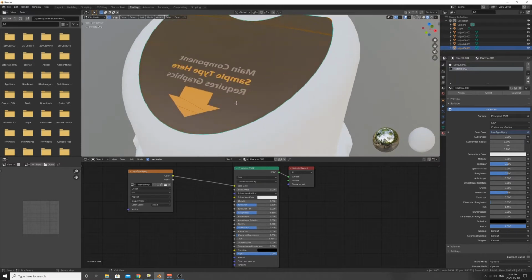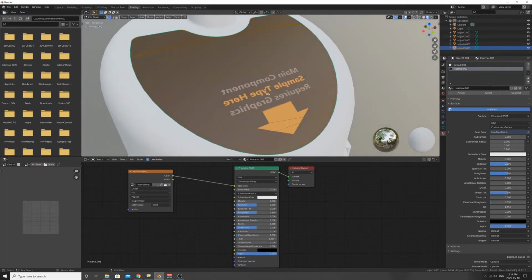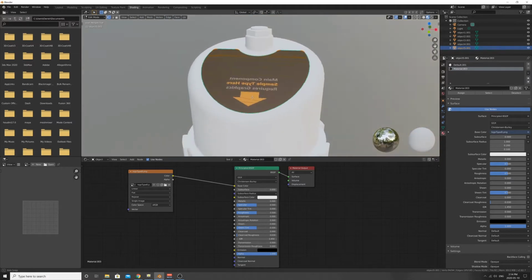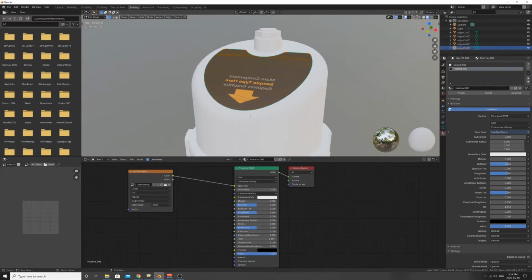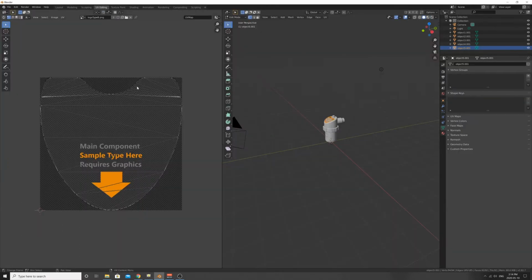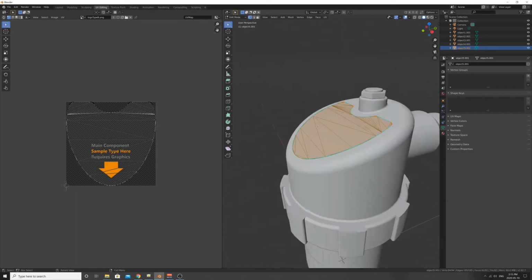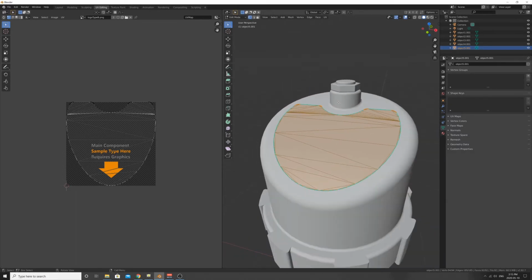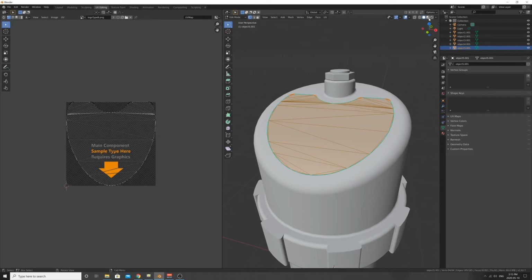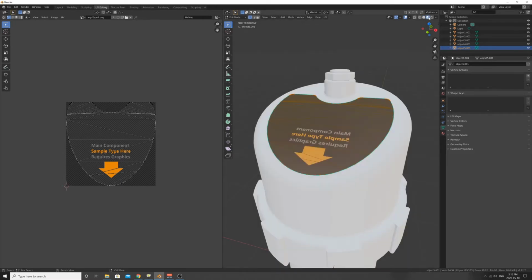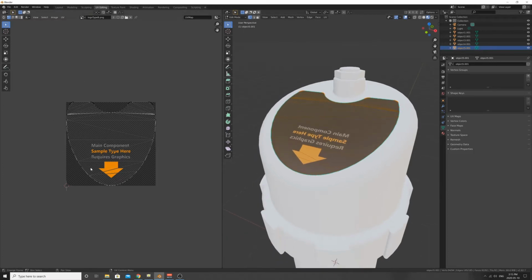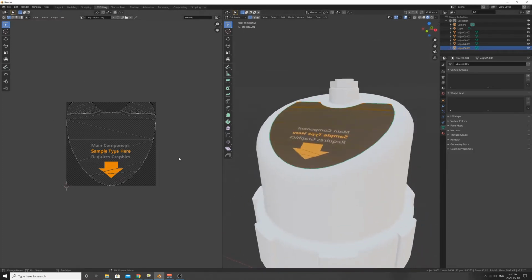And you can see what happens here is that, hey, these textures are flipped. It's not correct. So in order to resolve that, we have to go and fix our UVs. So we're going to go over to the UV editing tab, and by default, MOI will export UVs for you to use. Press period on the right hand side here, and up at the top right, we can click on the second material ball, and that's going to allow us to preview the texture while we're in this UV mode. But we need to adjust these UVs so that the texture is facing the correct direction.